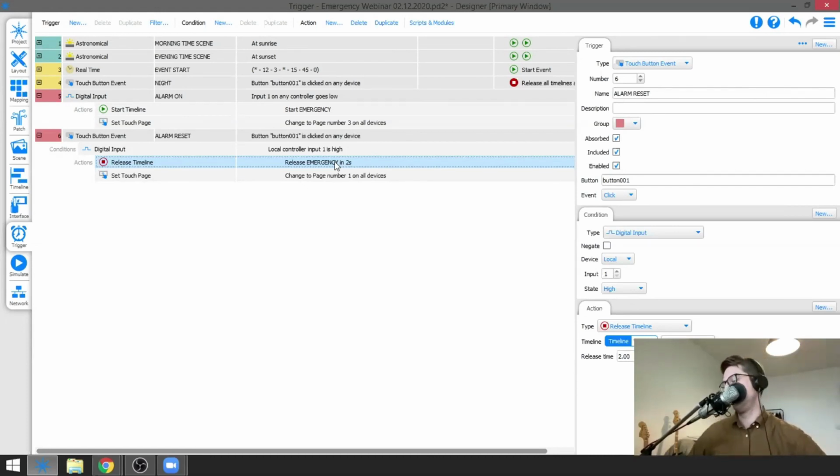Yeah, maybe to add to that, what we have seen happening is where the firewall is connected behind the UPS. So even if the power fails, the controller will still run, but because it's connected to the UPS, it will receive a trigger from the UPS when the mains power goes away, and therefore it can start to dim the lighting, or it can turn some lighting off, by sending out the other DMX values.